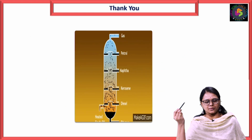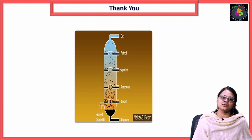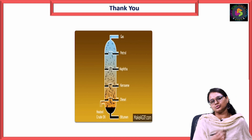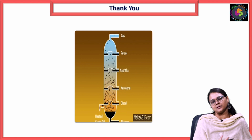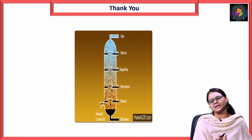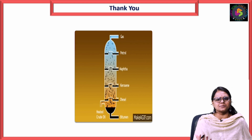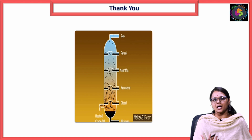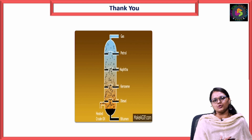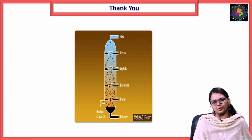So this is what we understood in distillation: mainly when to use distillation and how to know whether distillation is preferable for an unknown sample or not. Most probably at industrial level, they already have a proper setup for the separation of components. If you're doing R&D, then you have to generate data theoretically by using Raoult's law, Dalton's law, or alpha AB, that is relative volatility.